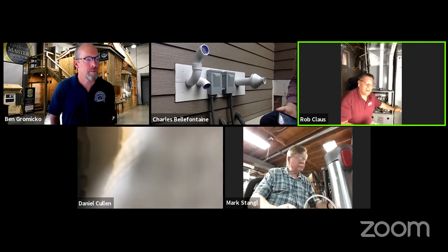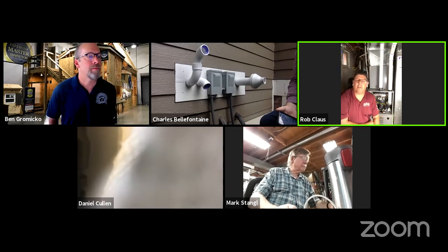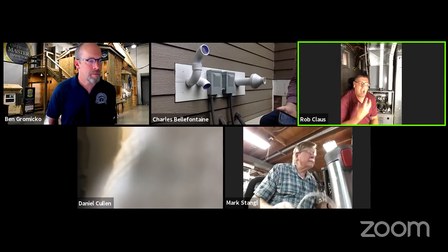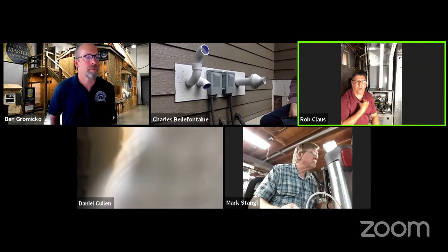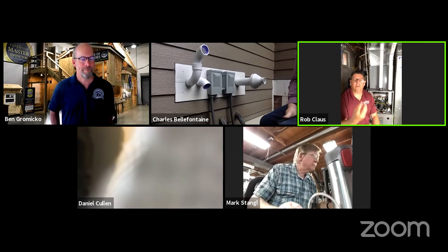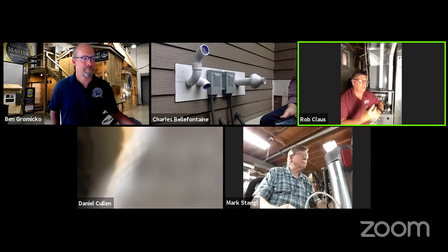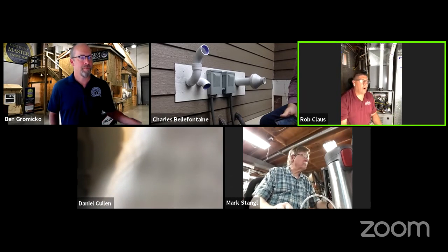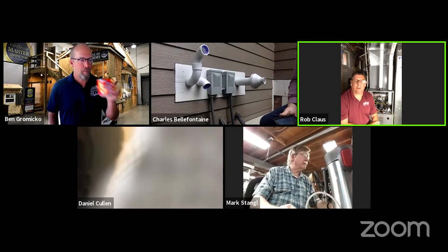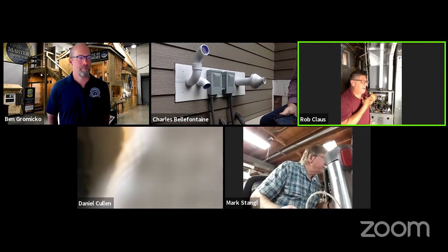In this particular furnace, I have a hole here in the cold air plenum, and I can always find a seam up in the warm air side. Do a delta check. My goal in 30 years of experience is everything I do is replicatable. Somebody else can do the exact same thing I did. I try not to be technically exhaustive with such fancy equipment that, oh, look, your equipment measured to this ppm, and oh, this equipment measured to this ppm. You found a gas leak. I didn't find a gas leak.